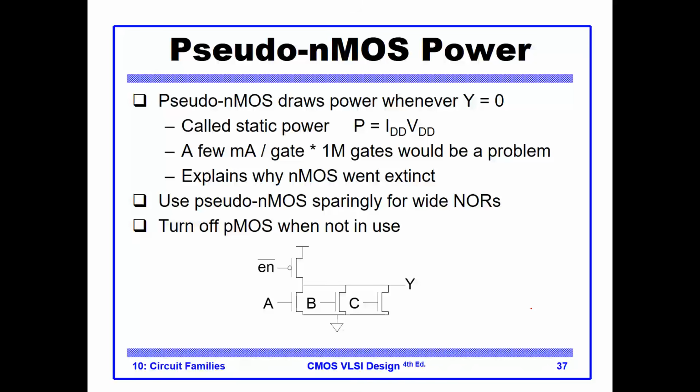Another improvement to the previous design, instead of having a ground here, you can remove the ground and use an enable signal here. And basically, this enable signal will have a value of 0 to turn this PMOS on whenever you don't have a 1, I'm sorry, on the input, so that you avoid this short current.